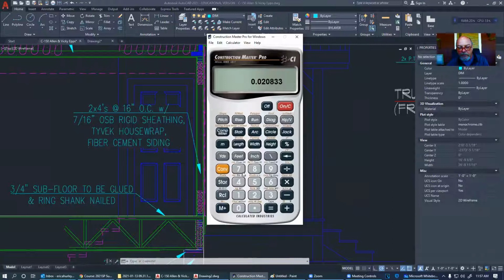Times 7 foot, 8 inches. I forgot what it was. Yeah, so that's right. I had that right to begin with. So that one multiplier, 0.25, and I forgot how to get to it now. 0.25 divided by 12, times 93 inches is 1. There we go. So yeah, I had that right. That is the multiplier, 0.25 divided by 12. So remember that multiplier, 0.020833. That is the multiplier to get you to our 1/4 inch scale.